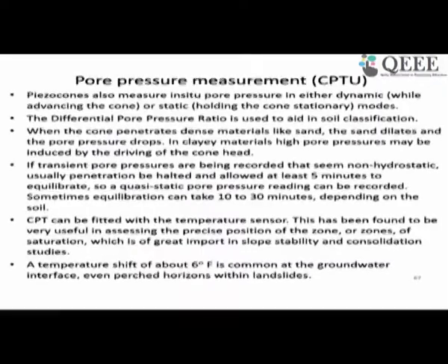Now this particular CPT is a mechanized way of doing the investigation, where you directly insert or penetrate a cone into the ground continuously and record tip resistance and sleeve friction through some kind of instrumentation. Now if you add some additional instrumentation like pore pressure measurement, it becomes more versatile.